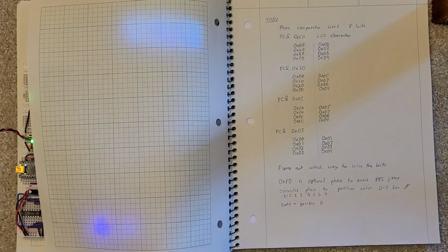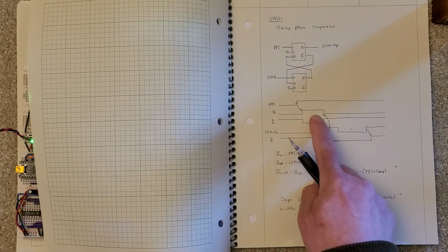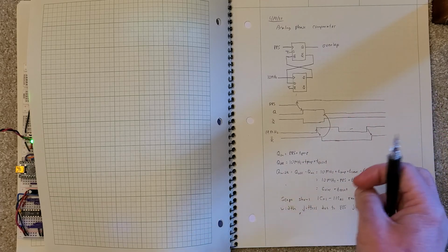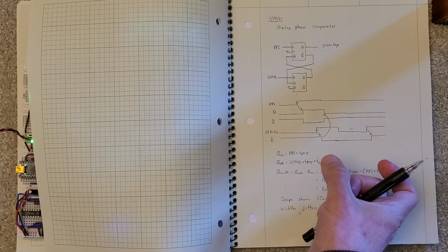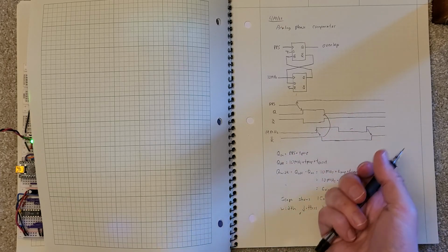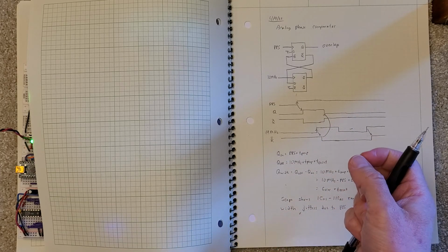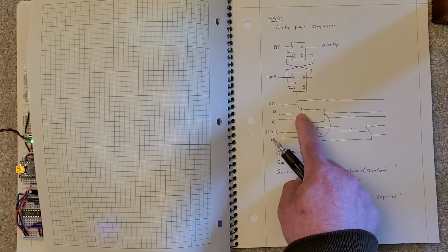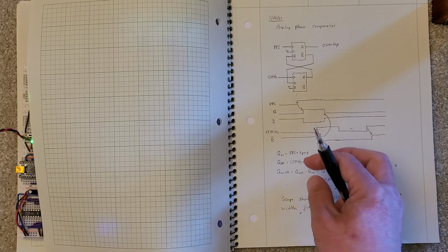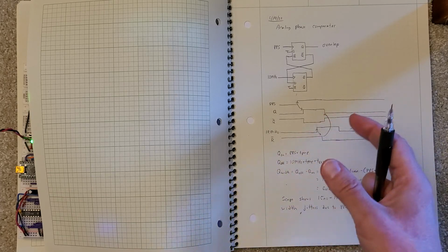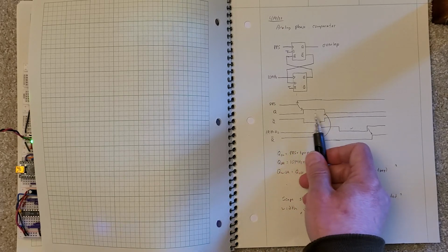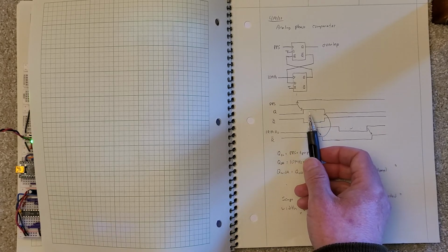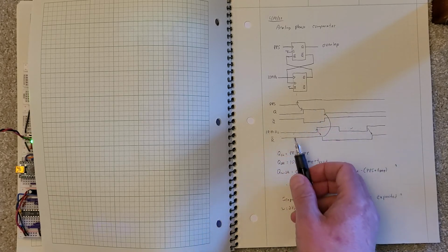So what I wanted to do was then take this pulse, and I can fire it into a capacitor with constant current, which will change its voltage depending on how long it's on. And then I can measure the voltage, and then I can short out the capacitor, reset it to 0, and wait for the next pulse to come in, feeding it constant current to charge up the cap, so I can measure the voltage again. And that would give me a time value, to the 10th of a nanosecond, I guess, of what that offset is.